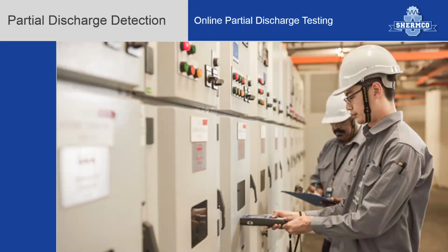Now, detection of partial discharge related faults is based on the principles of determining whether PD activity is at a critical level or not. Low levels of partial discharge activity are often present in assets at levels which may be considered acceptable, non-critical, or unlikely to develop into failures in a short or medium time period. So, understanding of the insulating material becomes very, very important when putting together an online partial discharge testing program.